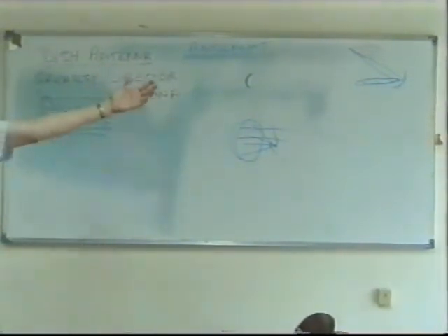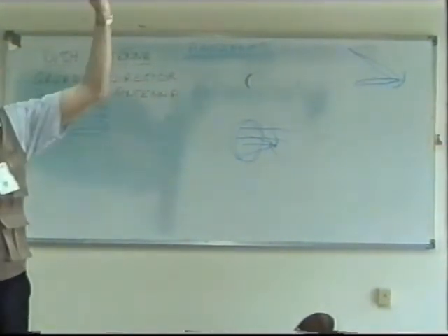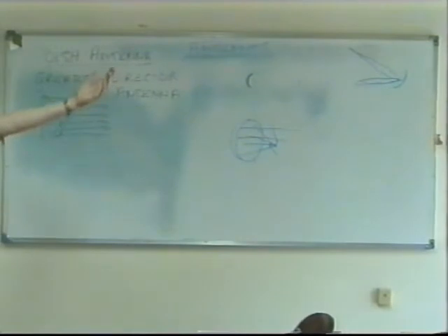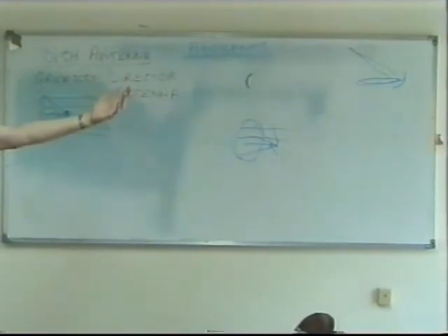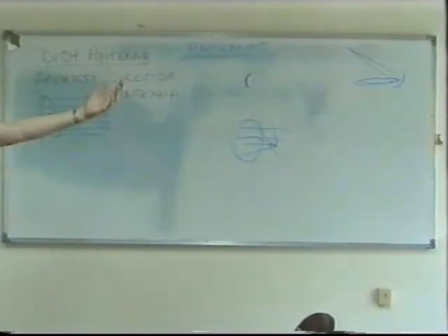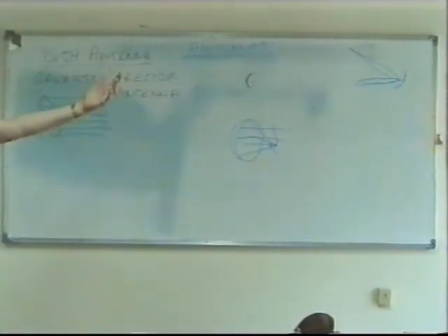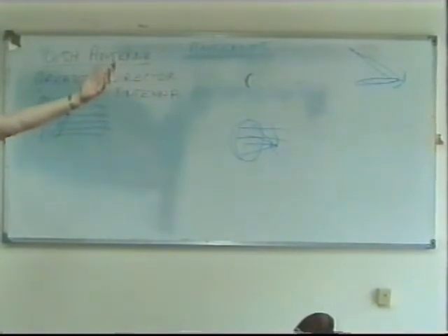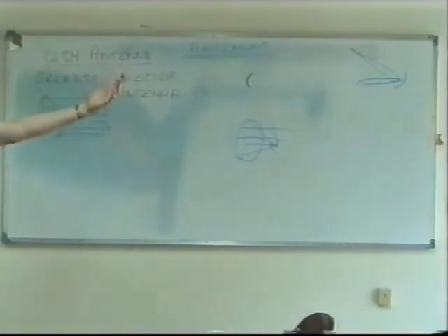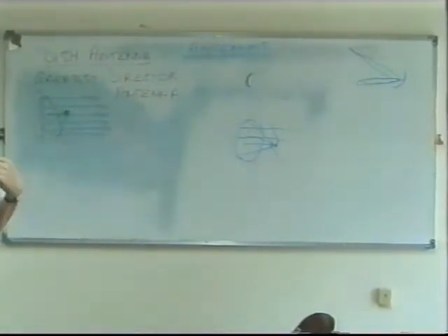And a well-designed dish antenna should have very small side lobes. A badly designed dish antenna will have bigger side lobes. You can go into the market, into the souk, and buy a dish, they sell them for 80 riyals. How much? 80 riyals. 80? 80. Now, do you think that's going to be a good one, or not very good? No. It might be okay for your TV reception, but we would expect to pay more than 80 riyals if we wanted our microwave point to point, wouldn't we?